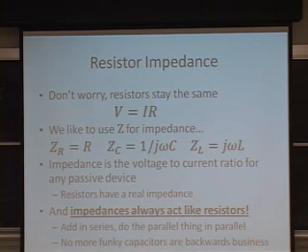And so now we can add resistors and capacitors that are in series. We can just add R to 1 over j omega C, and that's our impedance of an R and a C in series, for example. So they start to become easy to deal with. We now have all these blocks that we can treat just like complex resistors and put things together.